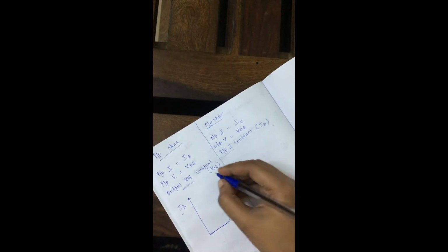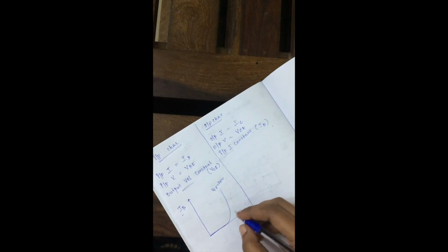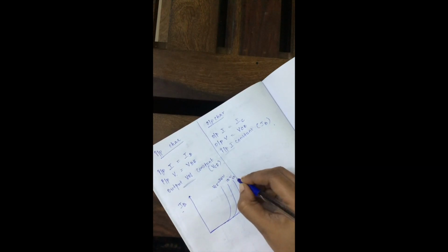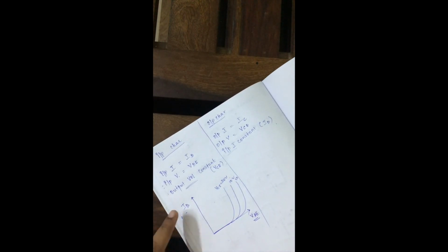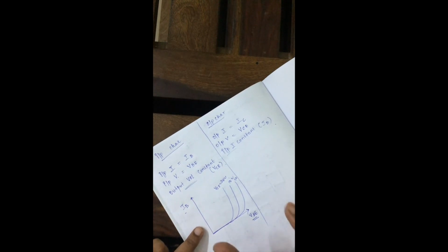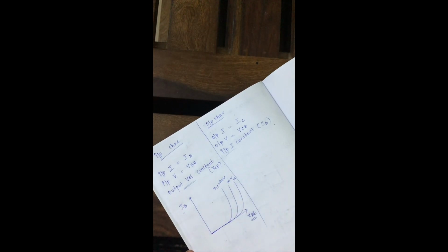Here VCE is made constant, so you can make it like 20 volt. So next, when VCE is 10 volt, then you will have a curve like this, again 5 volt. Okay, so here, like the previous condition, the input circuit is acting as a PN diode in forward bias condition. So till 0.7 volt no current will flow, then once it reaches 0.7 volt the current starts flowing.